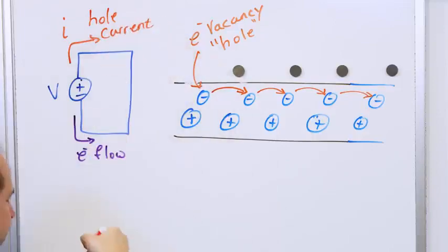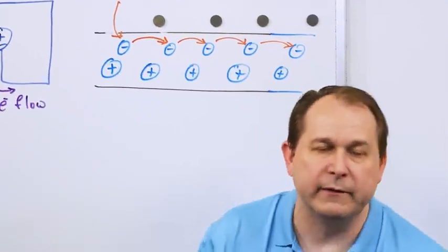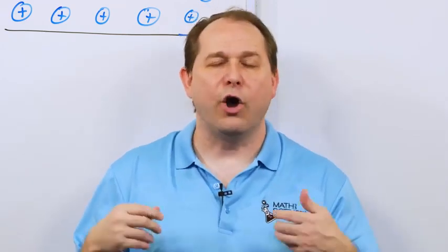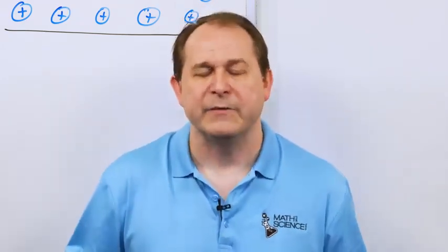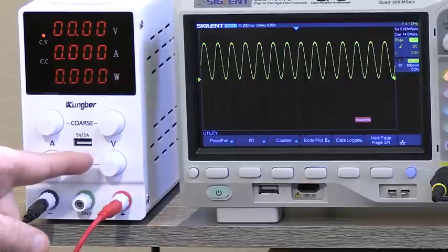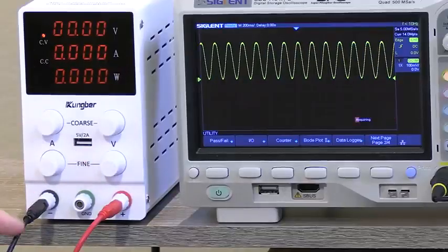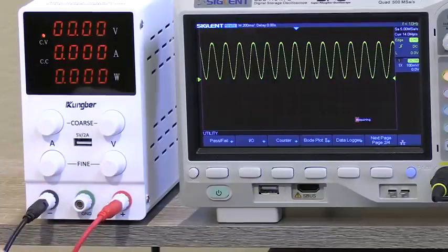Right? When you're studying engineering and when you get into circuit design, the current that we refer to is always the positive current flow. And it's just a convenience thing more than anything. When I look at this power supply, I can say that there's negative electrons coming out of here, or I can say there's positive fictitious charges coming out of the red one, because they're going to be the same thing.